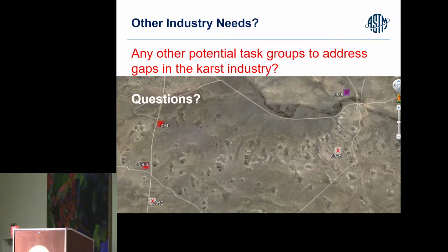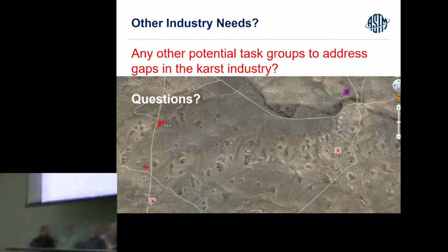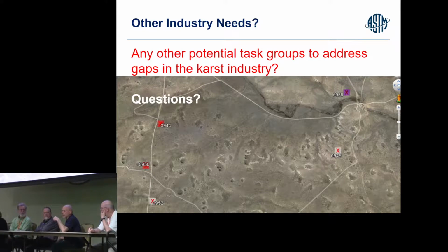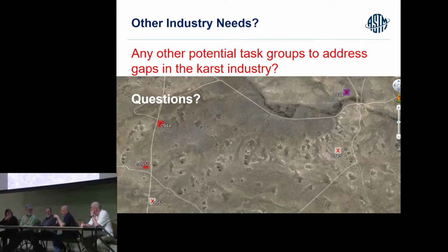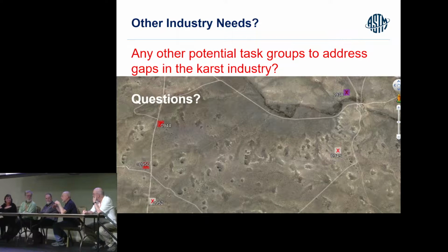Thank you. There is, but what happens is, and I mentioned this in the short course I taught on Tuesday, that in karst terrains, when they're undeveloped, when it's raw land, they tend to absorb more water than non-karst terrains. And as the rainfall amount increases, they become more and more like the non-karst terrains.